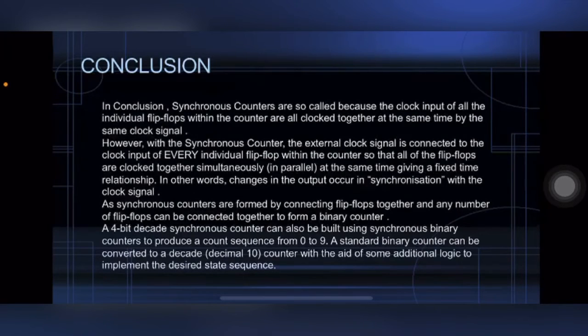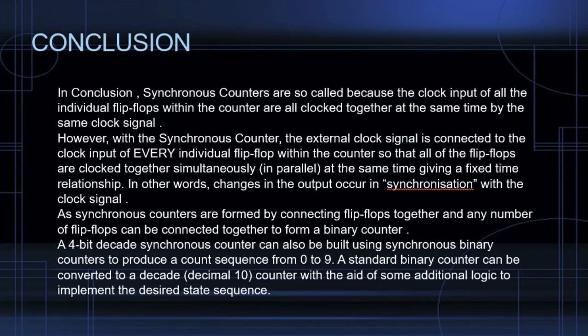So in conclusion, synchronous counters are so called because the clock input of all the individual flip-flops within the counter are all clocked together at the same time by the same clock signal. With the synchronous counter, the external clock signal is connected to the clock input of every individual flip-flop within the counter, so that all of the flip-flops are clocked together simultaneously, giving a fixed time relationship. In other words, changes in the output occur in synchronization with the clock signal.